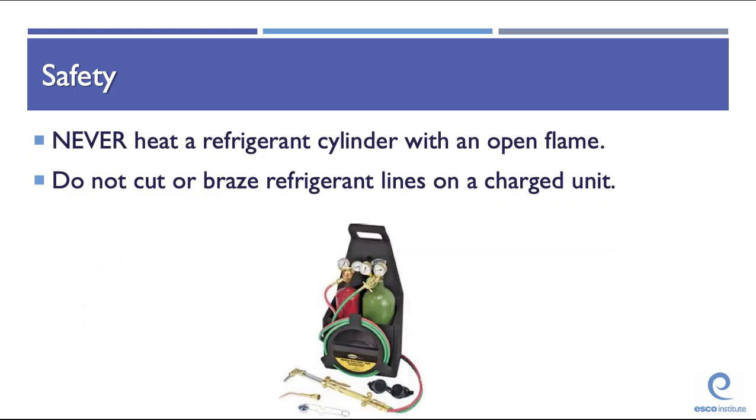Never expose refrigerants to open flame or glowing hot metal surfaces. At high temperatures, refrigerants can decompose and form acids. Hydrochloric acid is formed if the refrigerant contains chlorine, and hydrofluoric acid is formed if the refrigerant contains fluorine. If oxygen is present, it's also possible to form carbon monoxide, carbon dioxide, and phosgene gas.